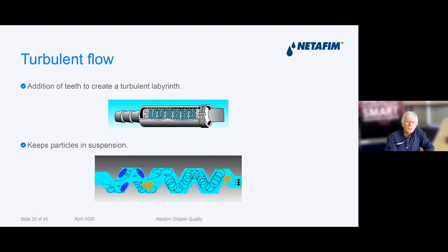And that keeps particles in suspension. You can see on the bottom line there, where I'm pointing to now, the water enters that side and it keeps all the particles that are in that water in suspension and doesn't allow them to be deposited on the walls of the dripper, and they exit and carry on through. Okay. With your laminar flow, that was not the case. Any particles that were in the water would be deposited on the walls of that dripper.